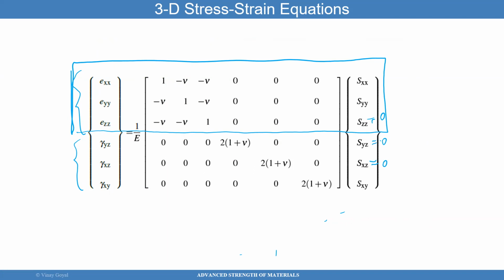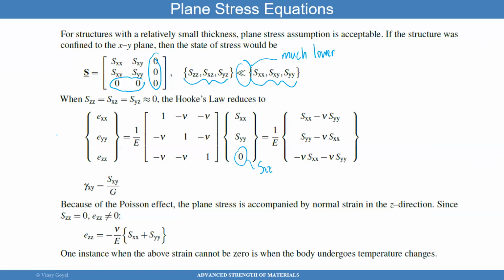That's easy. That's just saying that gamma xy equals sigma xy divided by G, the shear modulus. Since these ones are 0, these shear strains are 0. So I'm not going to look at those. I can look at the last equation easily, equation number 4, but I'm going to look at equations 1, 2, and 3. That's why everything looks so simplified here.